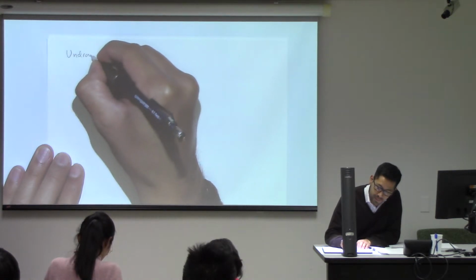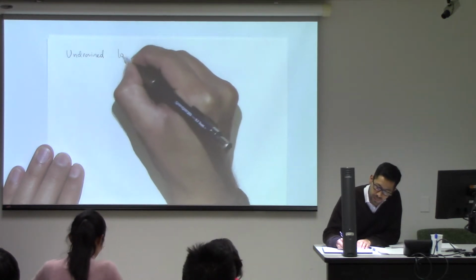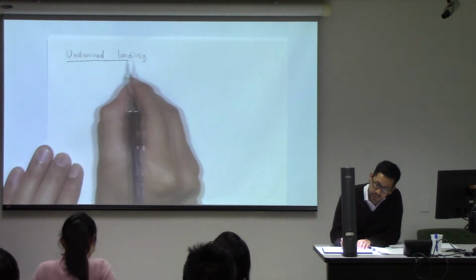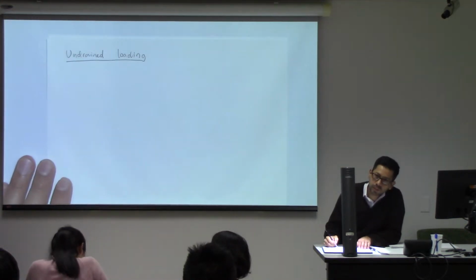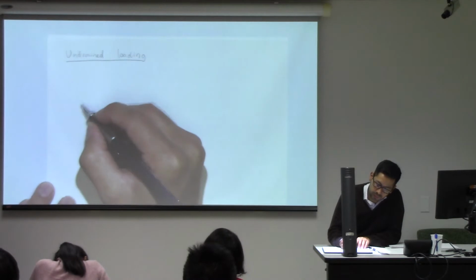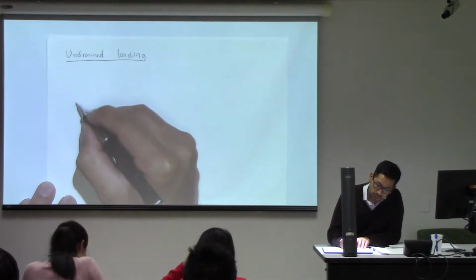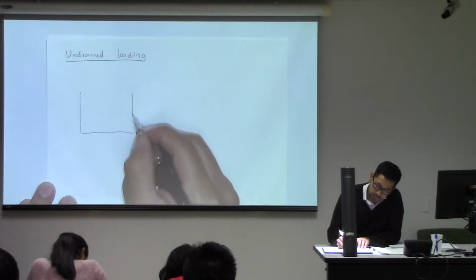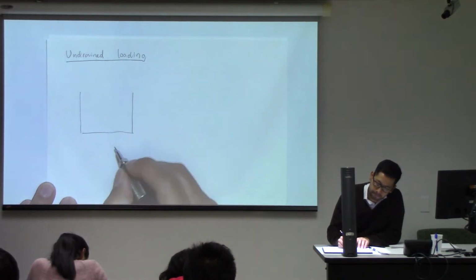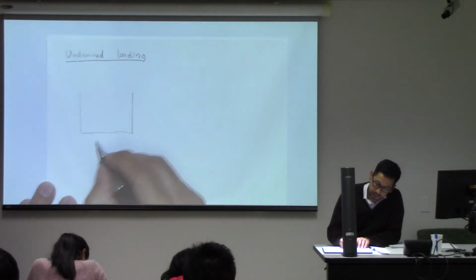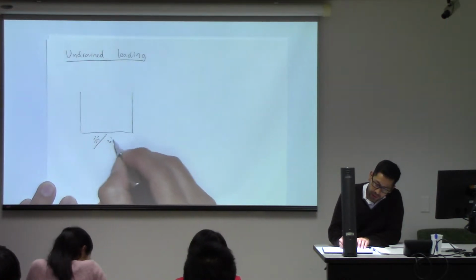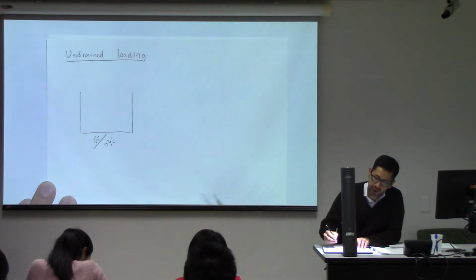It's when there's rapid dynamic loading on usually a saturated loose sand. Yes. Which causes a sudden buildup of a large amount of pore pressure, and so the effective stress of the sand goes to close to zero. Yeah. And therefore, the shear strength goes close to zero, and it starts behaving like a liquid, and things just fall into it. And where does that increase of pressure come from?